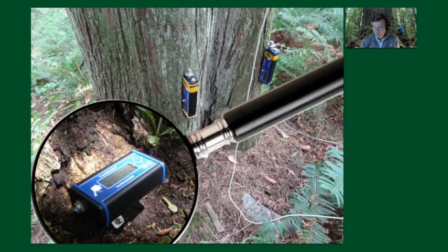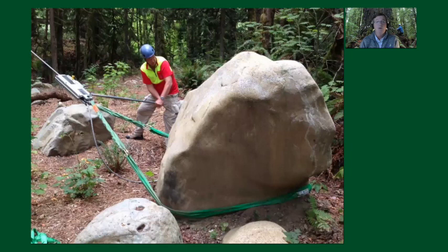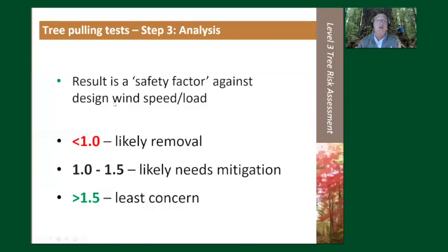We also know that we can extrapolate those reactions under a low load to how the tree would react under a high load. And then we compare that extrapolation to the wind load analysis. Once everything's set up on the tree, you need a good anchor, you need a strong man to pull hard on the tree. And I know this is a very simplified description of this method.